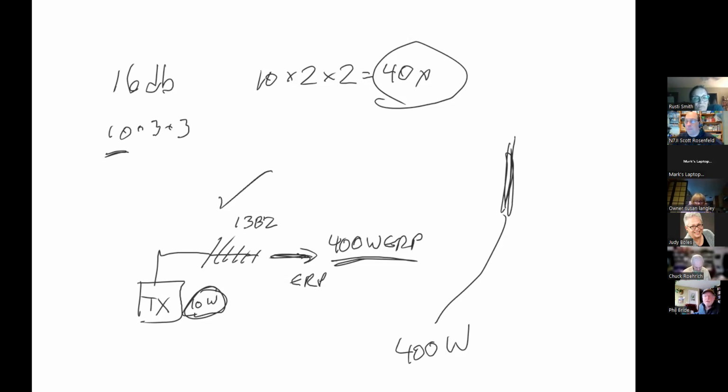So Scott, are our licenses based on our radiated wattage, or transmission? No, they're not. They're based on your RF power, not your effective radiated power. You're allowed to run 1500 watts into whatever antenna you see fit, unless there's something saying you can't. Okay, so it's based on the transmitter, not the gain. Correct. If you were to stuff 1500 watts out of your transmitter through that antenna, you're going to have a lot of outbound power.